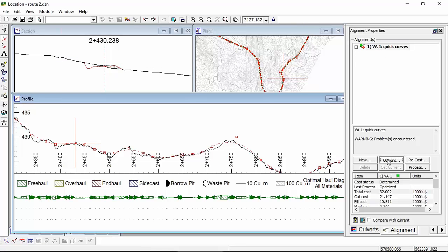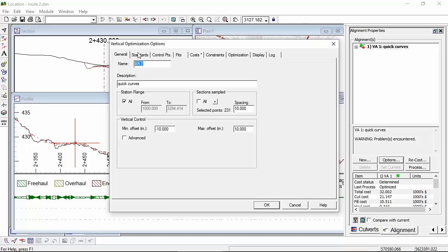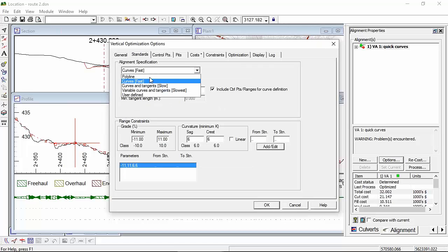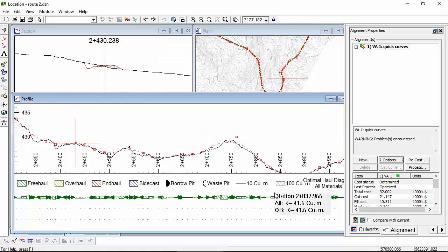There's another way around that. I could have used a polyline design. I can modify it by hand. Often forest roads are designed with short straight segments instead of curves. And of course, if I designed curves and tangents, as we saw in that other alignment, then they would be modifiable too. Back-to-back curves don't move around much because they're bumping right into each other, and so trying to move the alignment messes things up.